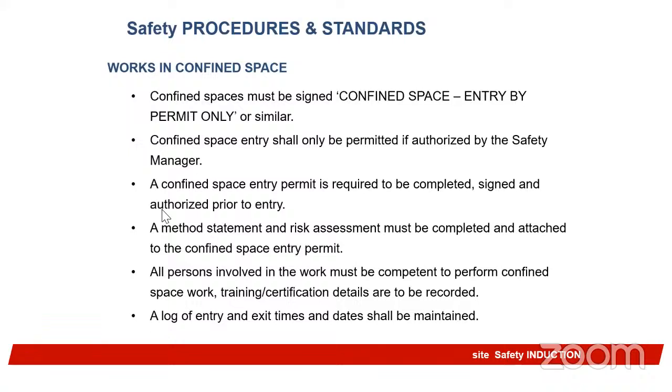Confined space must be signed confined space entry by permit only. Confined space entry shall only be permitted if authorized by the safety manager. The confined space entry permit is required to be completed, signed, and authorized prior to entry. RAMS, risk assessment and method statement, must be completed and attached to the confined space entry permit. It must be there.